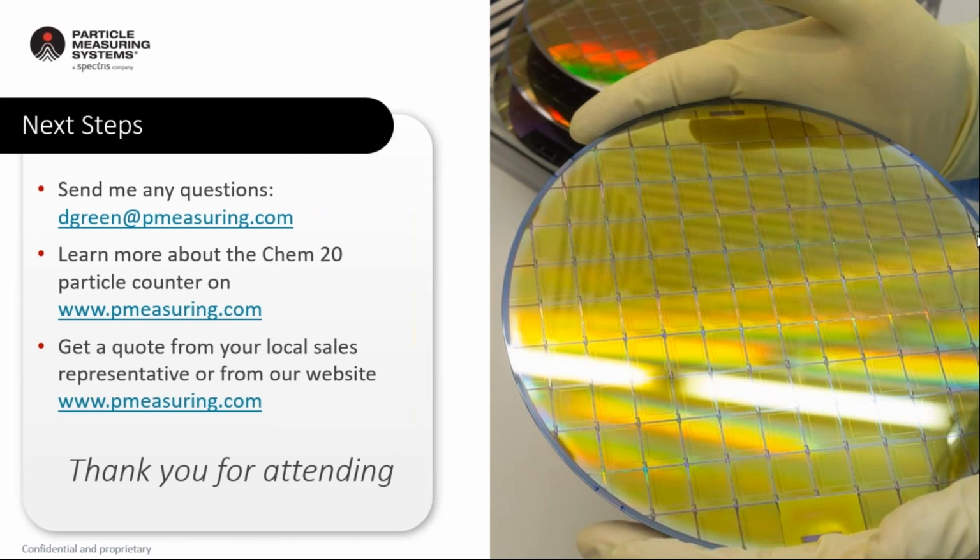The secondary place that people consider monitoring would be the location where the chemical comes back from the fab, because that way they would be alerted to the possibility that some tool in the fab or some mismatch in the balancing of the pressures and the deliveries is causing contamination to the chemical traveling past many of the other tools.